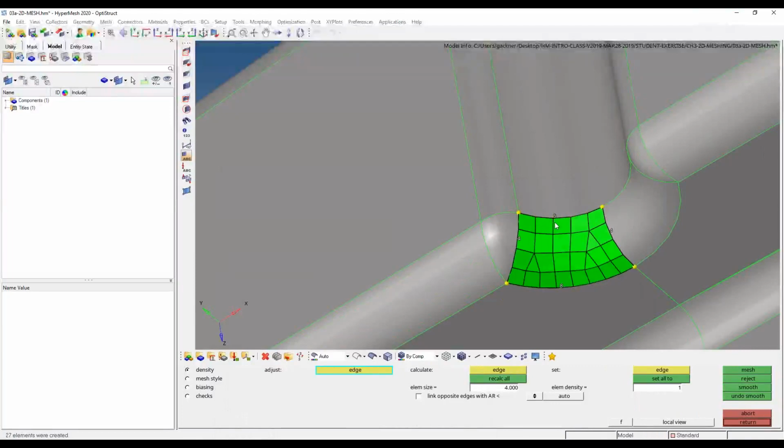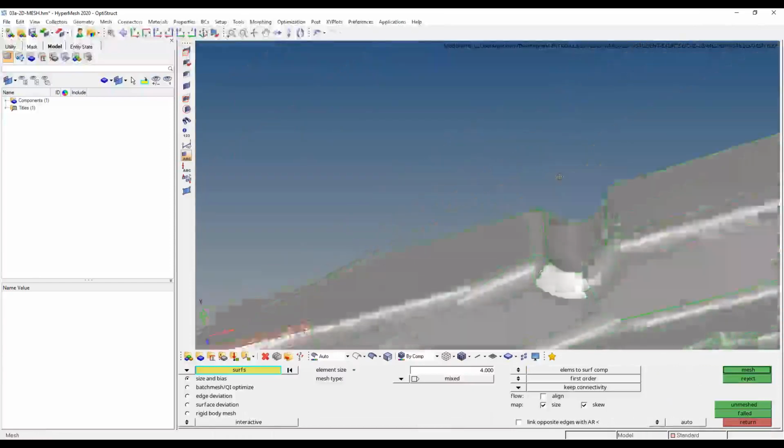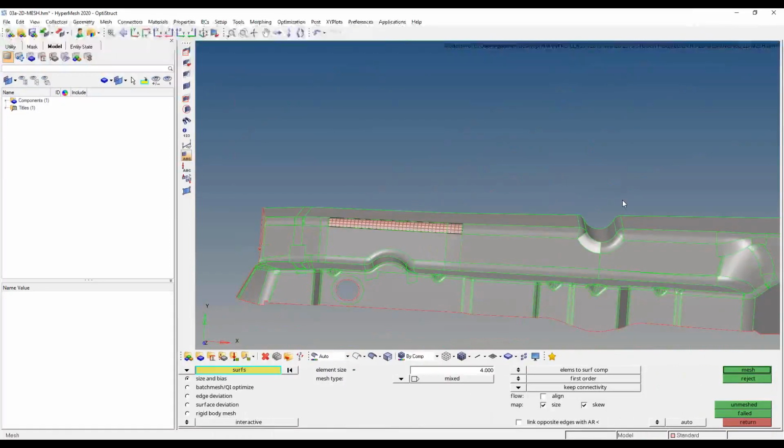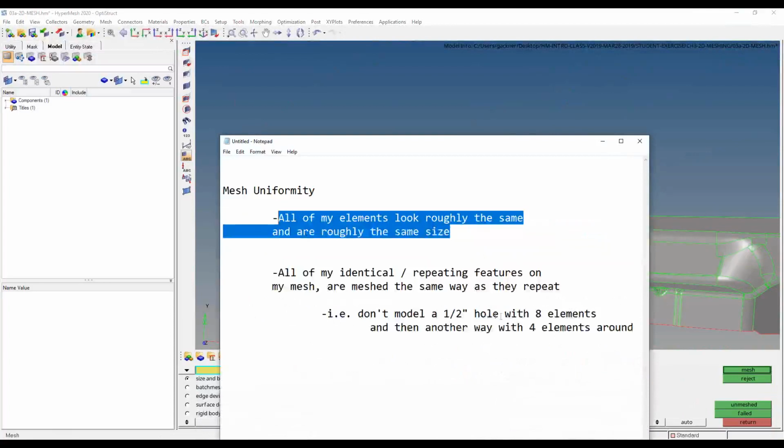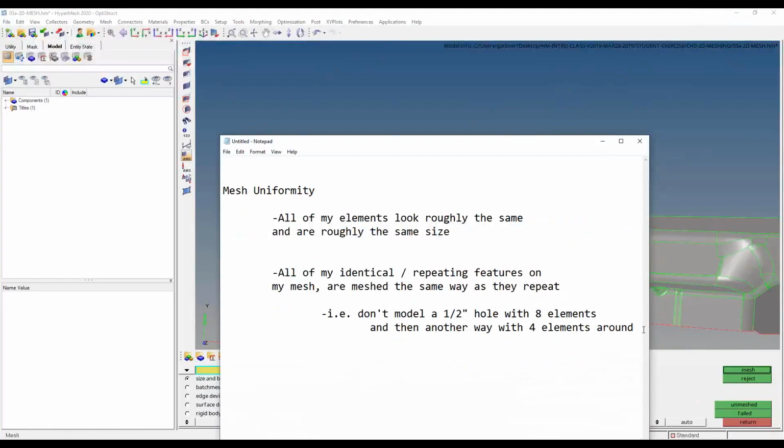It's just a simple click here and there, and then you can remesh it again to get that updated mesh body. Now, one thing I saw yesterday gives us a great opportunity to think about this. A question I saw some users had is, how do I determine my average element size? I'm ready to mesh my part. I want to start these FEA simulations, but I don't have the instructor sitting next to me telling me to mesh something with 4 millimeter elements or 10 millimeter elements or 1 millimeter elements. What are the decisions that go into that thought process, and how do we make those decisions? Really, what it comes down to in determining your element size is: what features do you want to capture?